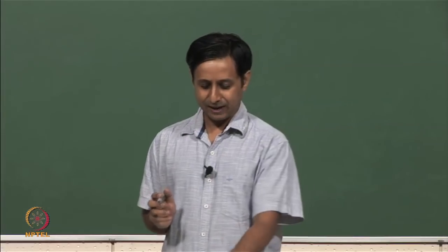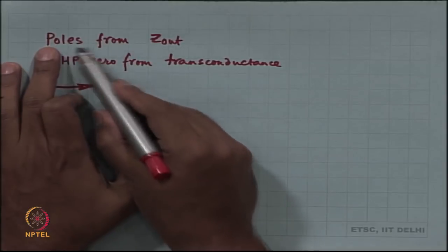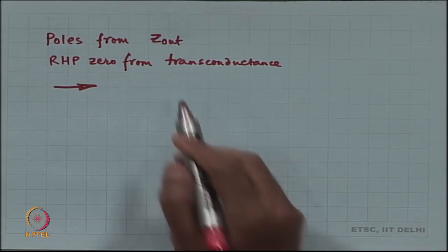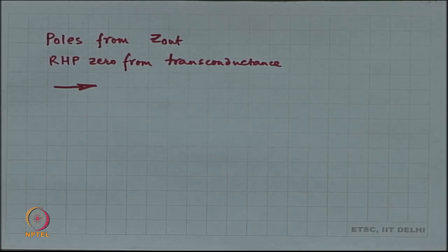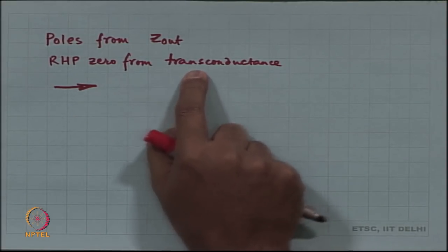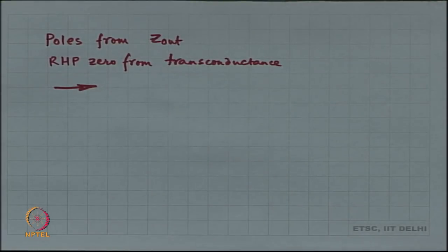Okay. Then after doing the DC stuff, you look at the output impedance and work out the poles, just the poles. Okay. If we had a shortcut, to find out just the locations of the poles, all right. And if we had a shortcut to find just the location of the RHP 0, then I can just write out the whole expression.